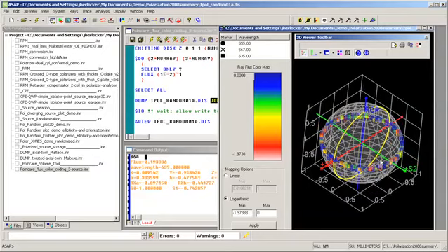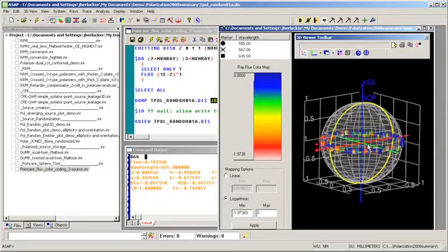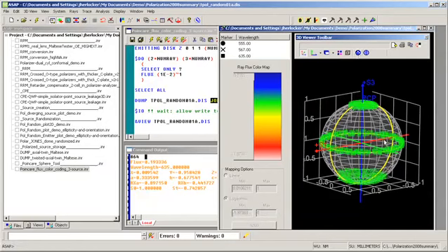There are many ways to alter the basic appearance of the Poincare Sphere tool. One further option that might be of interest is to turn off flux mapping altogether. If we want to see all of our rays again, we could change these limits, but we could also simply turn flux mapping off. And that's done using this button. So now all of our rays are showing again.